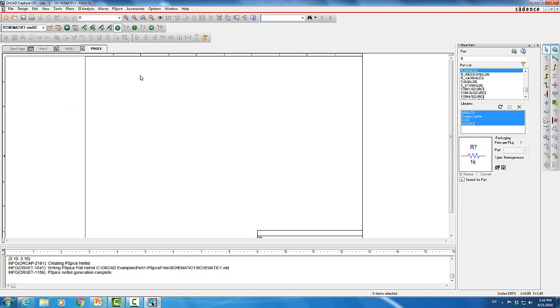All I'm going to do here is design a new circuit on the new page. So I'm going to add a part. I will come here where I have the library of adding a part, and I'm going to add VAC. VAC is basically the small signal AC source used for AC analysis, and we will keep this voltage to be 1 volt. So it has 1 volt AC, 0 volt DC, and basically this is used for the frequency response.